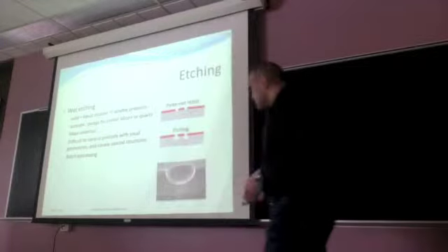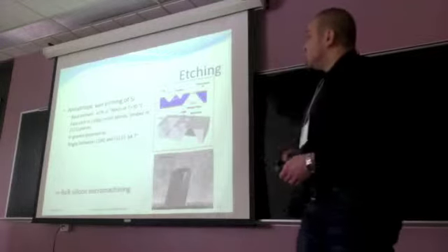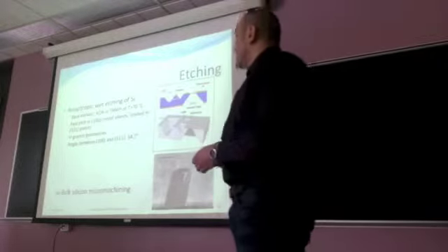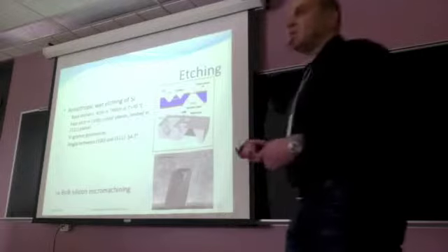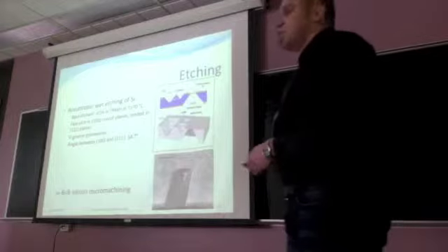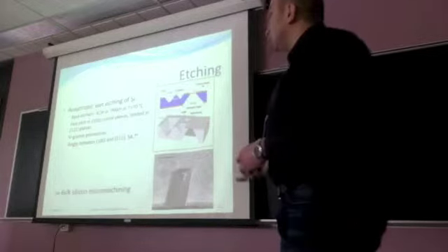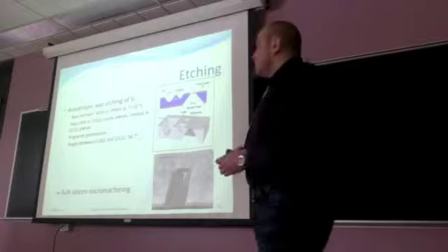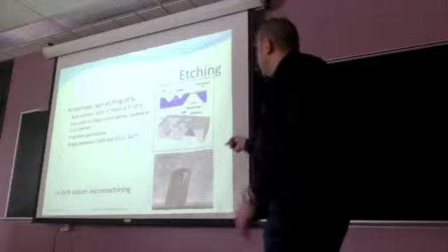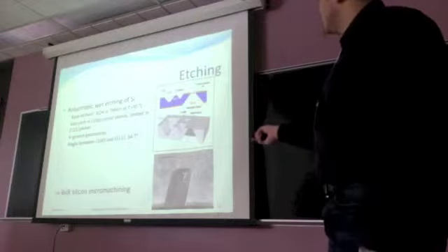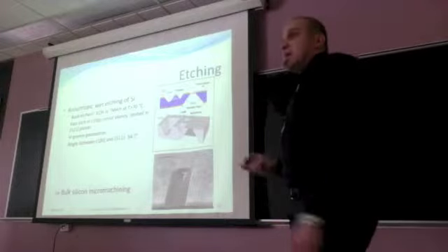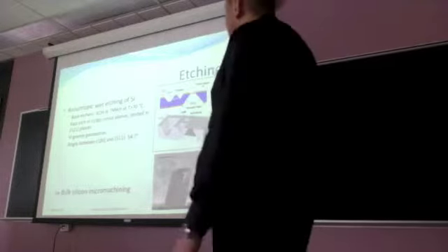So this is a special case of wet etching of silicon. When we use a base etchant like potassium hydroxide or tetramethyl ammonium hydroxide, the etch rate in 100 crystal planes is higher than in 111 planes. So anisotropic wet etching of silicon results in V-groove geometries. And you can see here on this drawing these V-groove geometries.